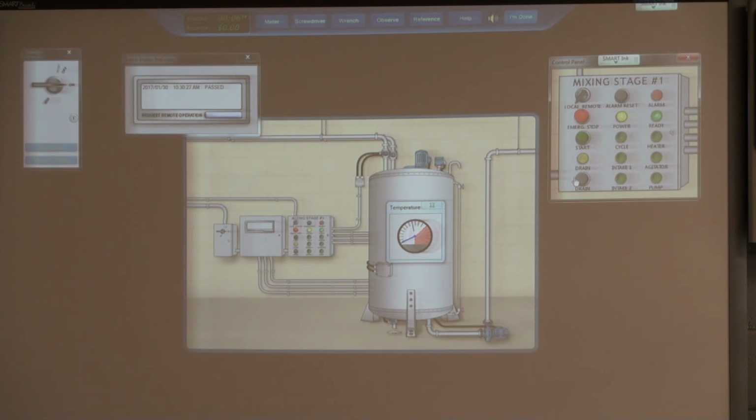And even to your point, Mr. Tanner talks about on output, which is on page 4, once the liquid reaches 70 degrees centigrade, the liquid must rest for 5 to 10 seconds. So it's kind of liberal in its time frame. That timer, I'll show you in the cabinet. When you replace the timer, you've got to make sure you set it to the right length, or else the times won't work right. So let's just take a minute to explore the system.